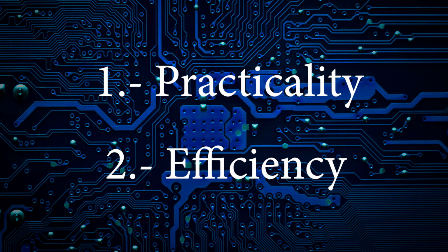In the case of efficiency, this is a more complex thing. In linear control, we vary the internal resistance of a semiconductor like a transistor. This becomes very inefficient because to reduce the power of a load, we also have to increase the resistance of the transistor, which means power dissipated as heat. But in the case of PWM, instead of controlling the resistance, we only control the time in which a load is on. With this, we have a transistor with the lowest on resistance and we get the lowest dissipated power.